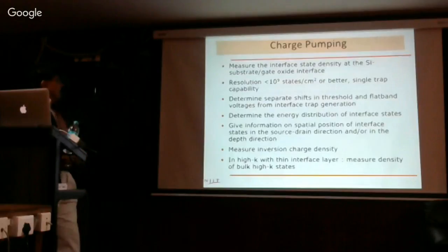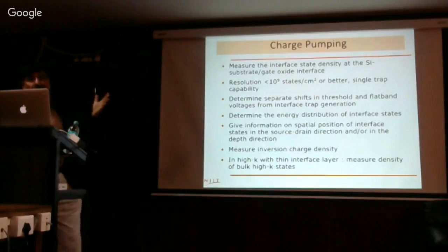So the other measurement is charge pumping measurement. Charge pumping actually is a very stable and very good measurement system that can be done with a pulse generator and the transistor measurement. So it measures the interface density at the substrate and gate oxide interface in a transistor.